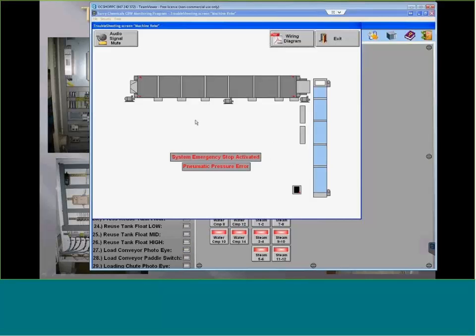So what you've got here, if you look, these little red dots are the e-stops located on this equipment. And when this error occurs, these little red dots are on. If the error wasn't there, these little red dots wouldn't be there. If it was a motor overload on this pump right here, this pump would turn red, and the overload inside the motor cabinet here would turn red.